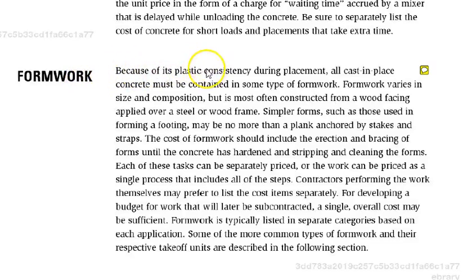Because concrete is plastic or almost liquid during its placing, you need to have forms to control where it is and its shape. And generally, you're going to use wood or steel forms to hold the concrete in place. Why wood or steel? You need something that's durable. Remember, concrete's a heavy material. You need something that you can bolt or nail together that can withstand the loads that occur when you're placing the concrete in the forms and when the crew is working with the concrete.